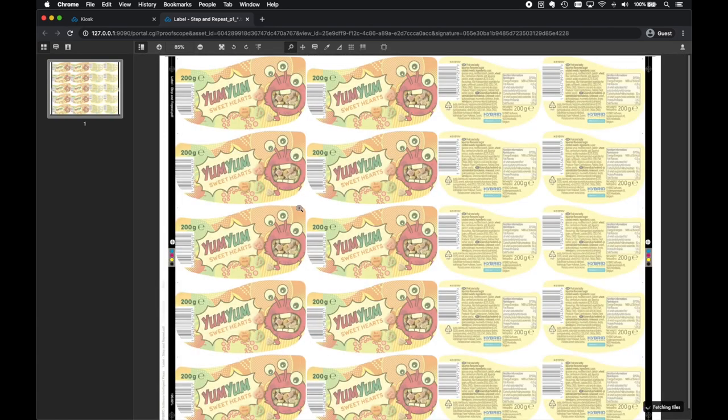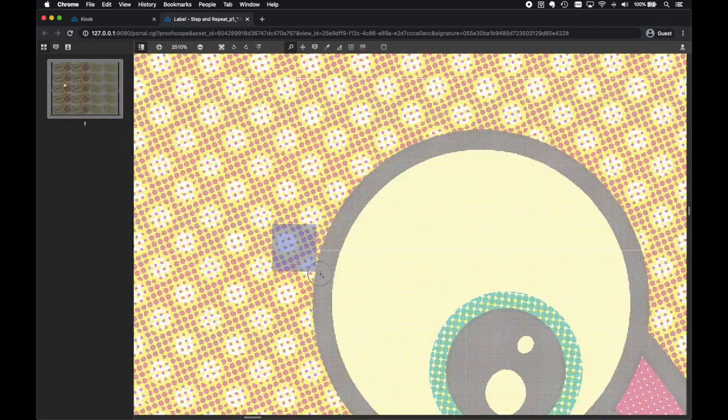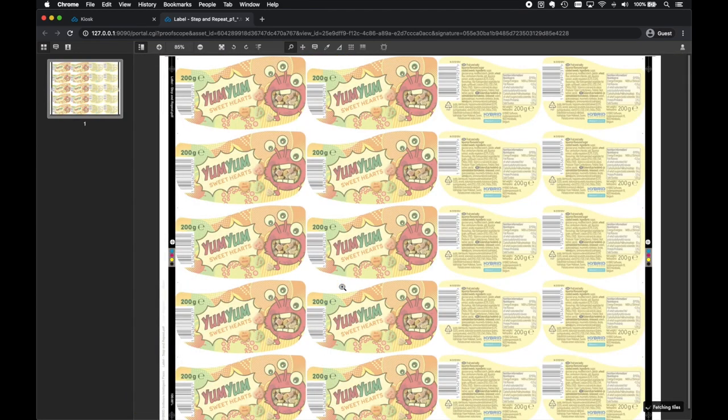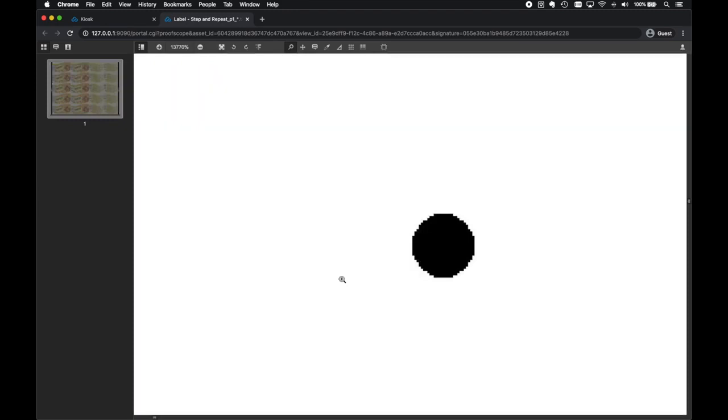The printed content has been marked with a medium density pattern, which promotes better ink transfer, more controlled dot gain, and can even reduce ink usage. You can also see the microdots have been protected. This is vital for automatic mounting systems because the cameras cannot recognize a microdot that has been processed by a surface screening.